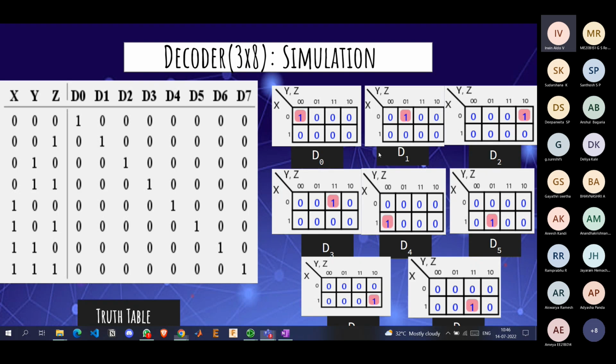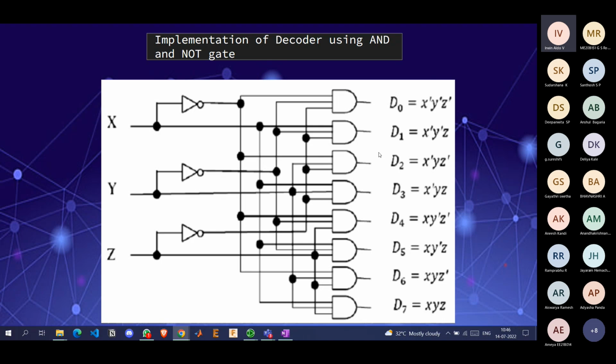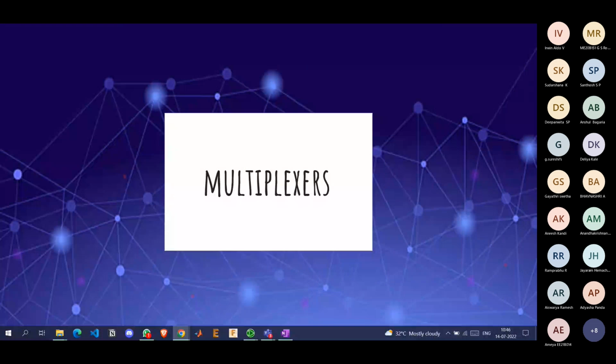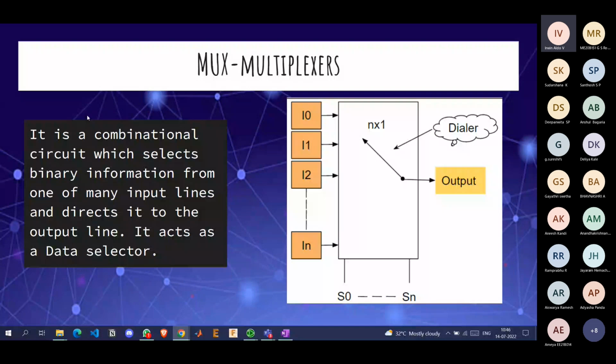Okay, moving on. Now this is the diagram. You can use it for future purposes. Going on to multiplexers. In combinational circuits, a multiplexer is a switch-like thing. Depending upon the control values from S0, S1 up to Sn, we will select the output. It's more like a gear. Depending upon what gear you put, your car goes in a different speed range, right? For different speed ranges, you will put different gears. You can think of it like that.